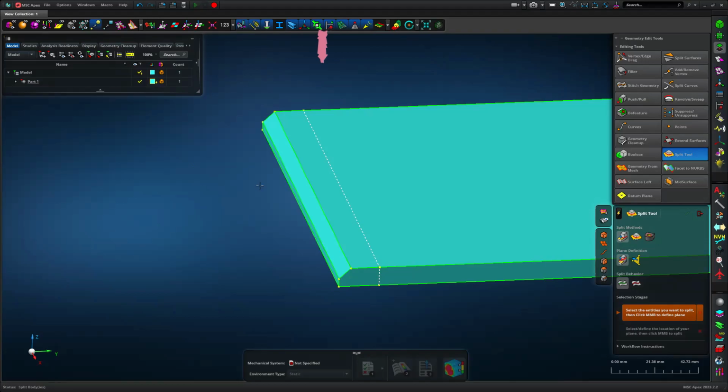Just the middle mouse button. You click outside the form. Now it is pink color. So with the pink color, you can just go to that vertical face and click. Now you give that value. Give minus 20, then enter. Minus 20, enter.